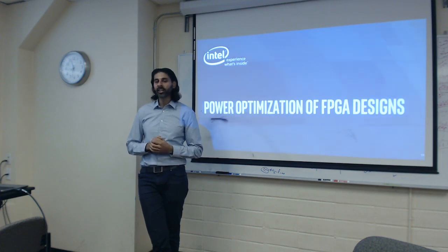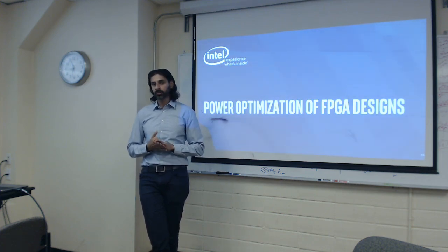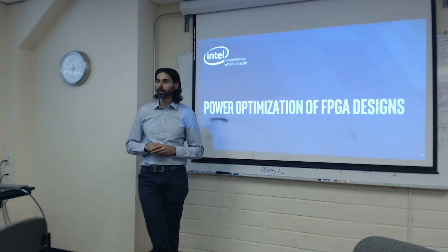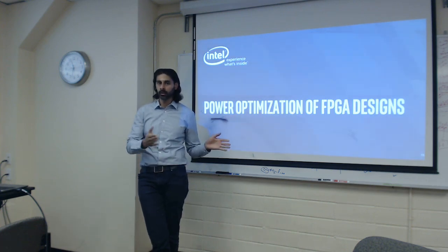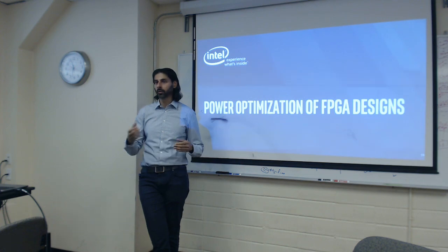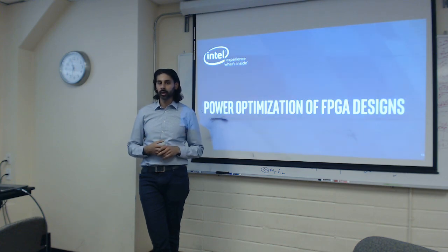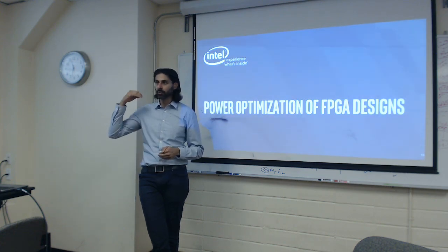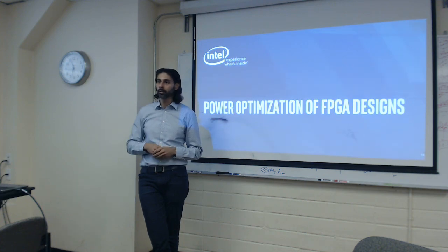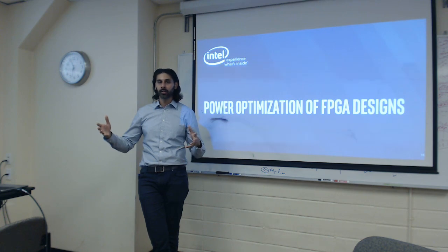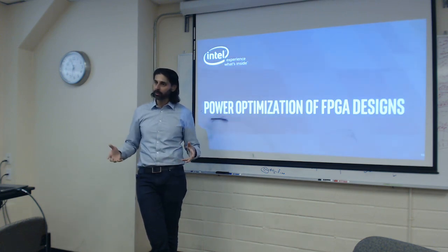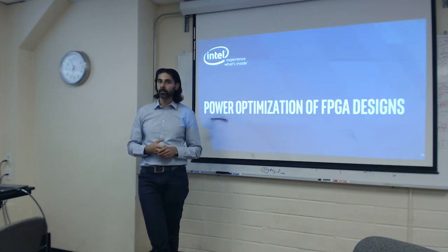Yeah, you have to remember, Stratix 10 is not just one part. I showed the biggest one. There is a spectrum of parts that are much smaller, and obviously the power is not 100 watts for those parts. Some of the niche applications are often not using the biggest, most powerful Stratix 10 FPGA. Typical applications for the bigger FPGAs are ASIC prototyping, for example, which is a different application altogether.